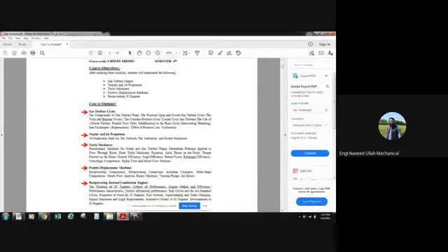So in gas turbine cycles we will be discussing the components of a gas turbine plant, and similarly the working principle, how the gas turbine power plant works, and similarly the practical open and closed gas turbine cycles. That is known as the Brayton or Joule cycle. The cycle on which the gas turbine power plant works is called the Brayton cycle or Joule cycle. So we will be discussing this in detail.